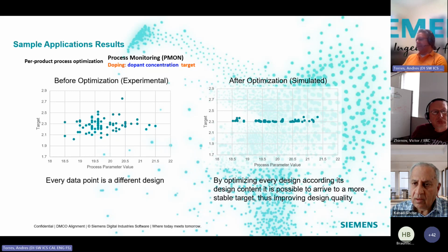No. That's actually a very good question. I think I have a slide that talks about that. What happens is that there are wafer-to-wafer variations, but in many instances, those wafer-to-wafer variations can actually be mapped to responses that the design has given the process conditions. This is why it's super important to have these three components. You need the characteristics of the design, and the characteristics of the process, meaning, for example, the temperatures, pressures, voltages, flows, and all of that data is actually collected at a per-wafer level. The measurements aren't, right? Because the measurements are only maybe one wafer per lot or something along those lines.